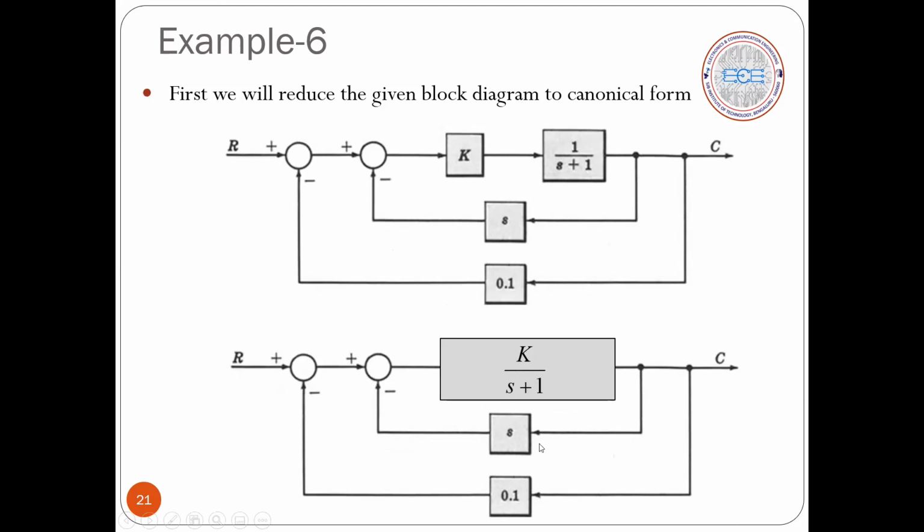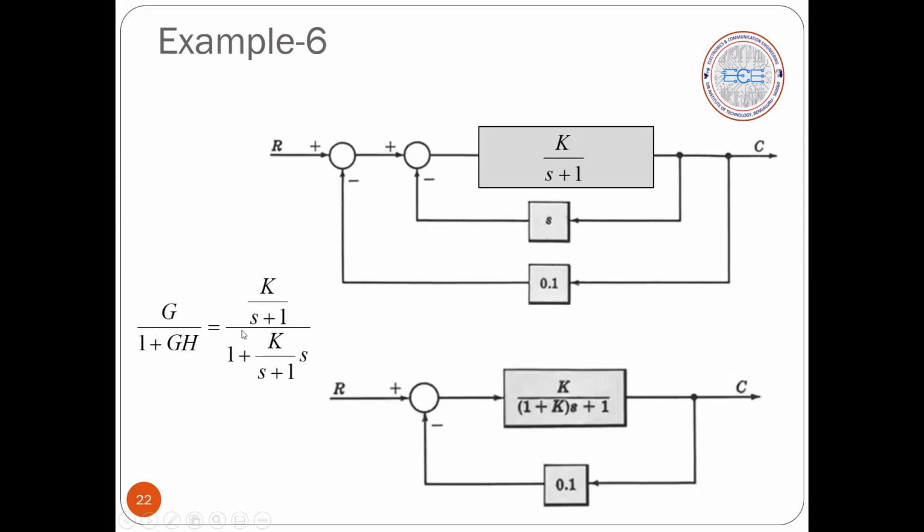And you can see that here it is a loop, a feedback loop, and the sign indicates a negative feedback loop. So this we have to simplify. We have seen the formula for simplification of that negative feedback loop system. The formula is forward path gain divided by 1 opposite sign. Since it is a negative feedback, we take plus here, the forward path gain into the feedback path gain. This is the loop which we are supposed to simplify.